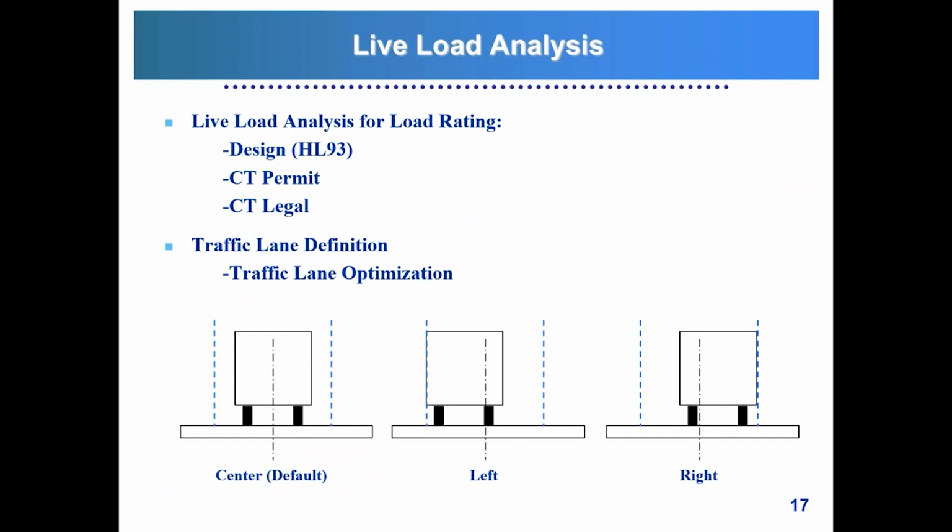For the live load analysis, we carry the live load analysis for the design loads and then also for the Connecticut permit and legal loads. And in MIDAS, once you set your lane definition, MIDAS allows you to have two options for how you want to carry your live load analysis. Basically the default option is that your truck will be placed in the center of your traffic lane. It also has an option that is called traffic lane optimization.